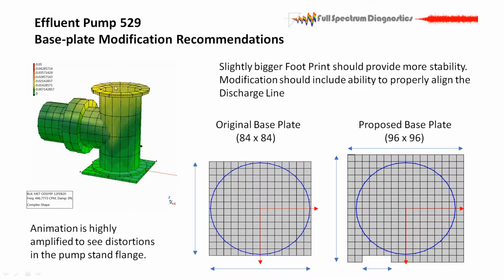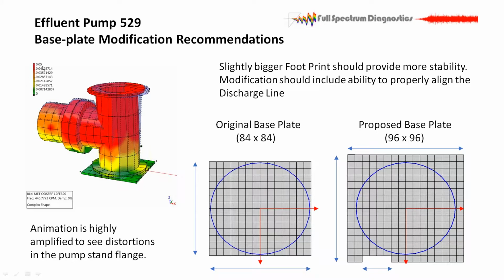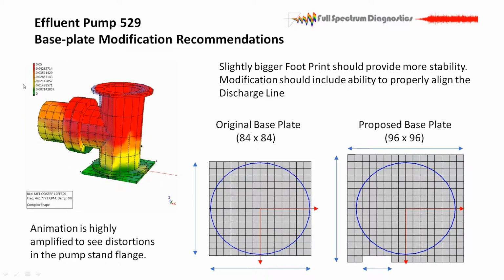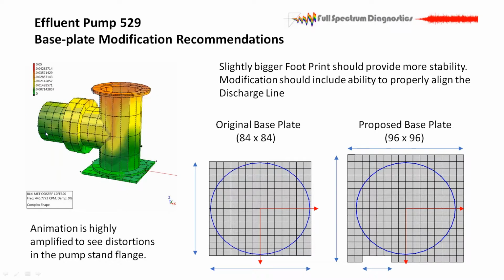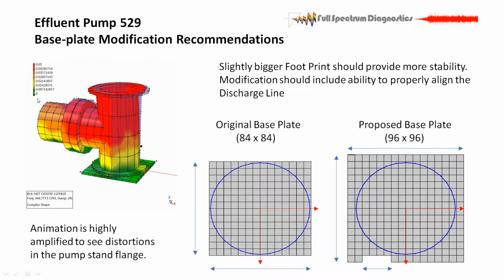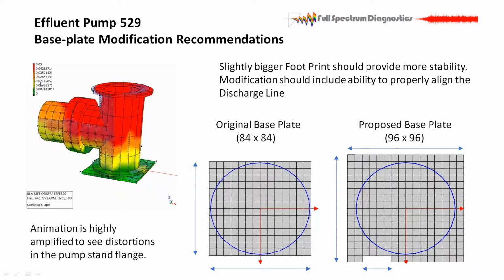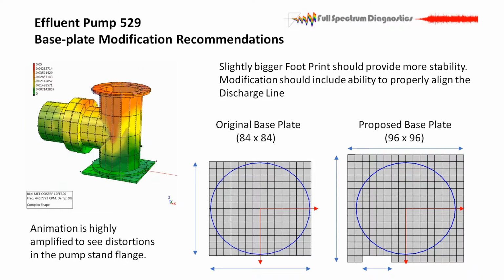Even after turning up the volume, my color contours went from a maximum of 0.4 inches per second down to 0.05. Any vibration in the base up to 0.05 is probably acceptable. And we're not getting that down into the base. We're getting something like 0.02. So 0.02 inches per second is about half of an alarm level.